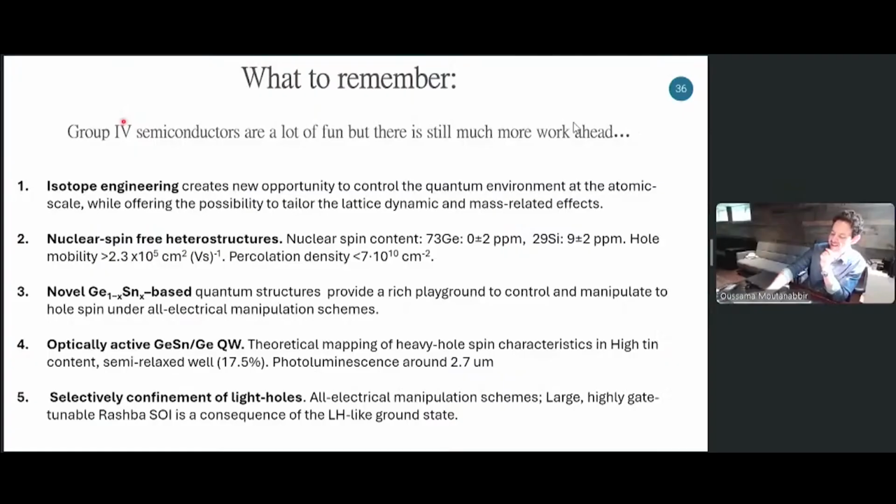We had a conference on silicon epitaxy. So to answer your question, I don't think we need CMP, to be honest with you, but based only on hole mobility measurement. My friend in CEA-Leti, Jean-Michel Hartmann, is working with the same silicon germanium heterostructures, the same composition, the same stack, the same thicknesses. He showed me his result in mobility measurement after CMP of the buffers. He has an industrial reactor, so he grows, takes the wafer, CMPs it, and puts it back.